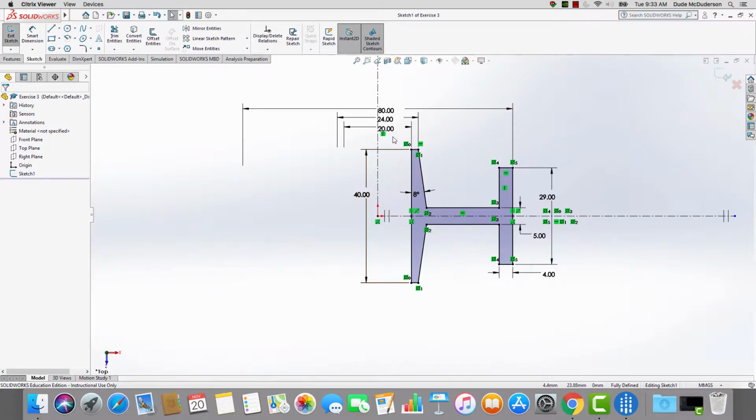The other thing I really want to show you, and again, we'll cover this as we do this step by step, is if you look at these three dimensions here, these actually refer to centerline dimensions or diameter dimensions, as some programs refer to them. Essentially, we are dimensioning across this center line. So if I highlight the 20, for example, the distance from the center line to the edge here is actually just 10 millimeters. But we're given a value of 20 millimeters. So rather than have to do the math, we can just input the diameter by dimensioning across this center line. Similarly, we do that with this point here and with this outside line, which gives the overall diameter of the wheel. This way we don't have to do math. Right now these numbers are fairly easy for us to halve, but if they had several decimal places afterwards, it would be much more difficult. So moving to a diameter dimension is going to be a lot easier. Everything else is pretty straightforward, and again, we'll cover this as we go.